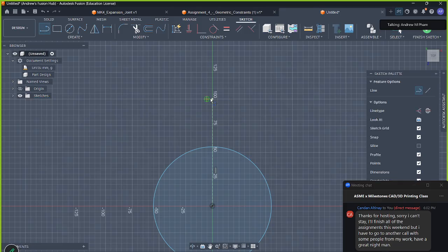If you went up a little bit on accident, you can add those constraints back in. So sometimes I purposely draw them in a quote-unquote incorrect position, and then I manually apply the constraints later. For me, it's honestly kind of a personal preference, because sometimes Fusion will make assumptions, and sometimes those assumptions are wrong, right?